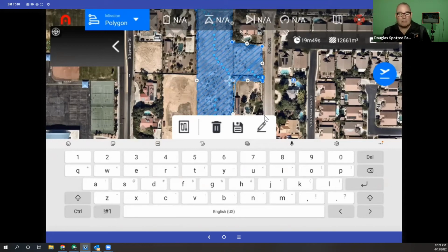Generally, we will set up the mission, lift the aircraft into the air, do a safety check with the aircraft by checking all control surfaces, and then we tap the blue button, which will upload the mission while the aircraft is in the air and start its flight. This way, we are able to accomplish our safety checks and also set up our mission for flight. So that's the first step in getting any of this overall set up.